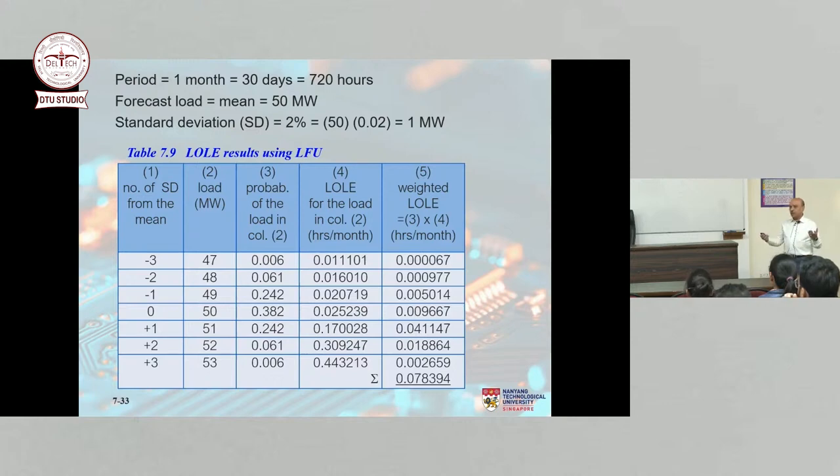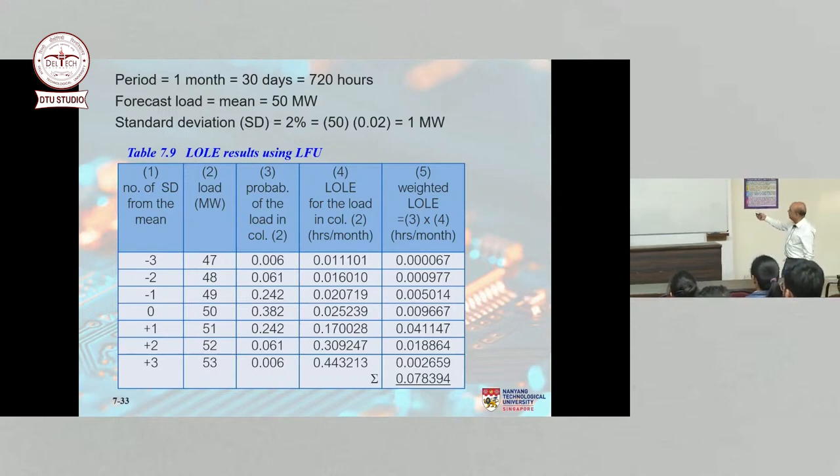Until now I'm used to only one calculation, correct? Now I'm doing it 7 times total instead of 1 time. So you will find that the risk for each of these loads using the cumulative outage probability table, yeah, the COPT is 1 and only 1. That's not changing, fortunately. It's only the load that's changing.